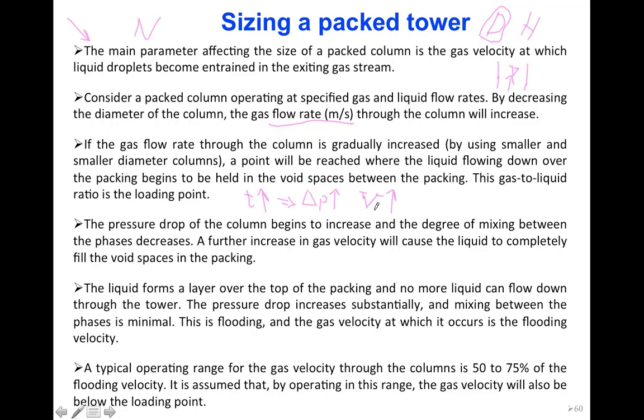So we have to stop the column, clean it, drain the liquid, and restart the column, which always comes with some waste of time, waste of money, and for sure some environmental impacts. So we always have to make sure. Like how we can reach flooding, either by very high velocity or a small diameter. So these are connected. The velocity will define the diameter or vice versa.